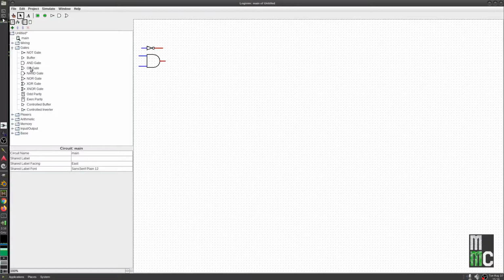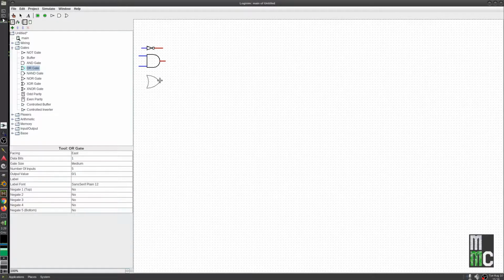We have the same thing with our OR gate. These are the logic symbols that you'll encounter all the time. The AND is this shape. An OR is kind of like an arrowhead. I can do the same thing here. I could change that to 2, but I won't. Instead, I'll just connect up some wires by clicking and dragging. And then the last one that we've studied, of course, is the XOR. It's right here. It looks a lot like the OR gate, but it has an additional line back here. And same thing. I'll just pull this out. So that's how you hook them up.